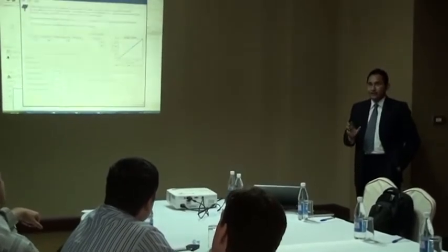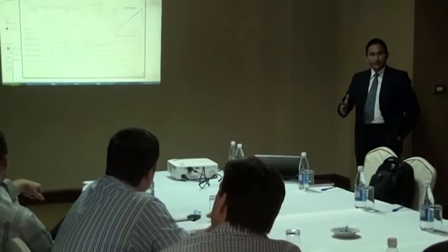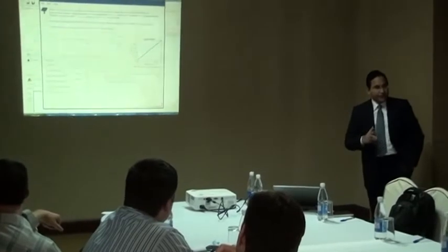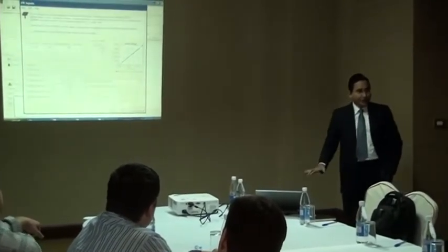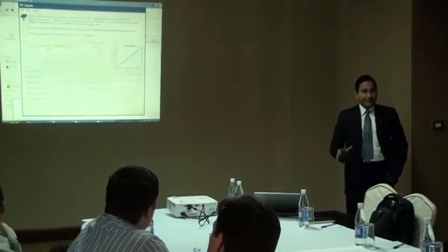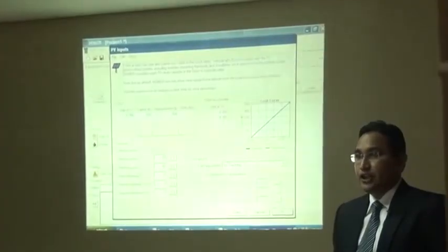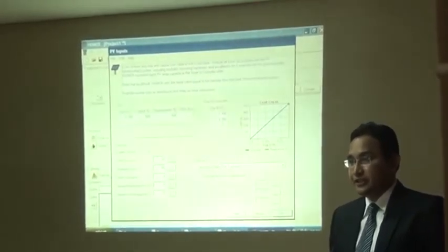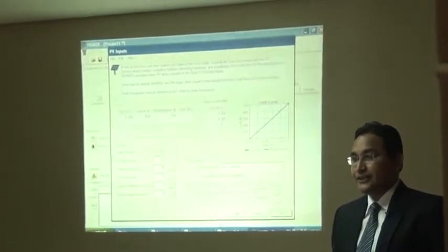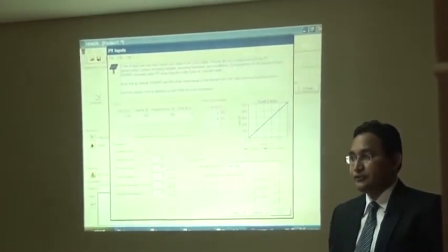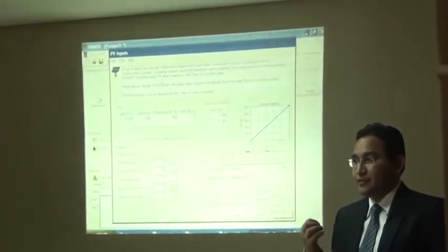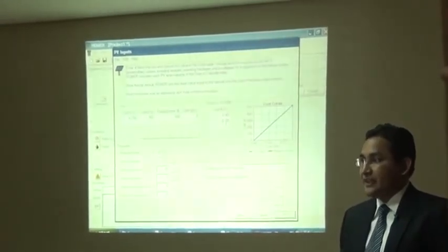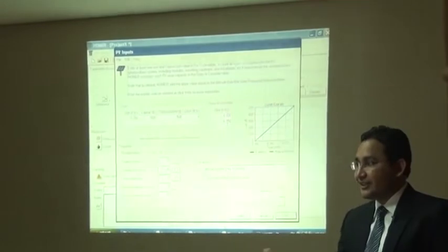Now you have to get real field data or field feedback on whether it's practically possible to acquire more land. If it is practically possible to acquire more land, then you go up to 10 kilowatt, 12 kilowatt, no issue. But if you cannot practically procure or acquire more land, then look at what land is available at the site and how many modules you can literally install there. And based on that, let HOMER decide what would be the best option for your battery bank size, your genset dimension, your rectifier dimensioning, your PV dimensioning.